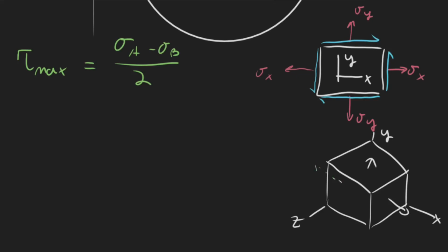It turns out this is a pretty good approximation if we have loads and forces acting in this plane, and if it's pretty thin, then things like bending aren't going to matter too much. And we could also have shears. This would be our shear here, and we'd have one here, and then the negative side, so this would go this way, and this one would go this way. But technically, even though we're looking at plane stress, it is still a 3D element.